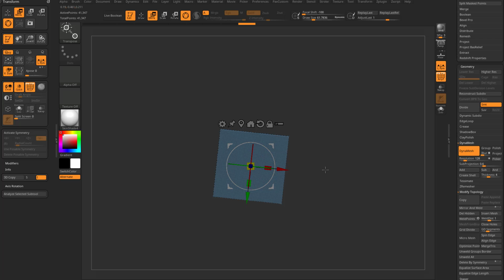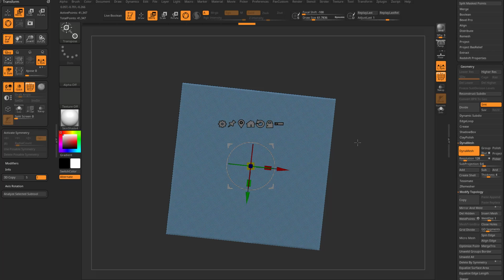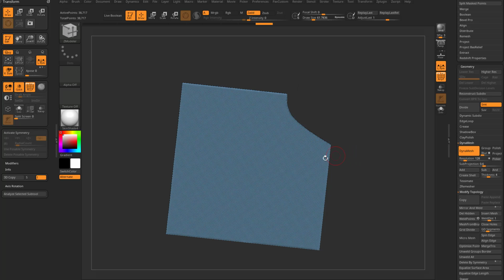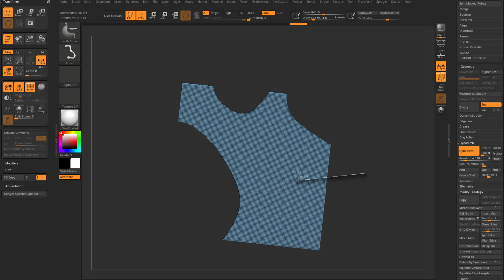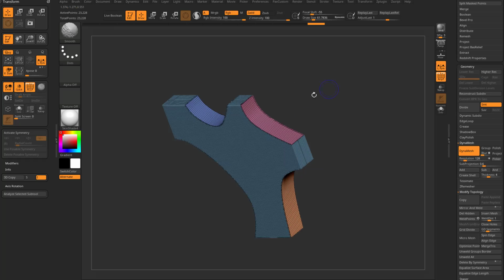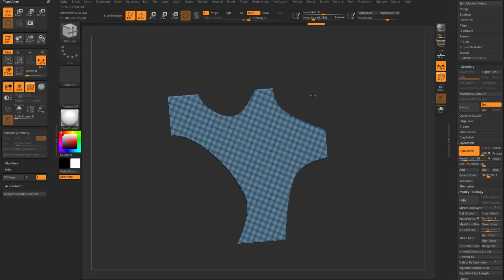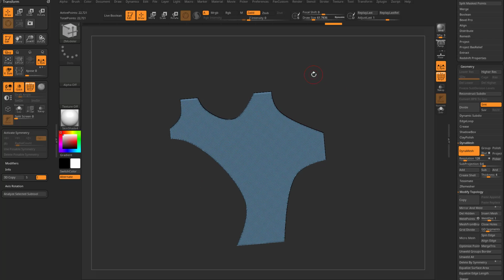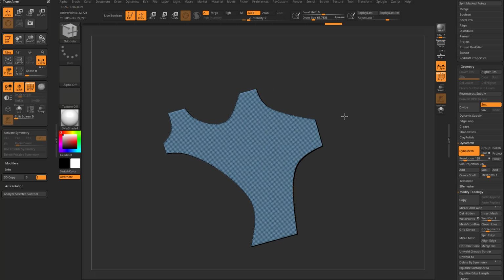And then click that Z or whatever axis you want to cut in. In this case, the Z is what I want. And that'll point that camera straight in the direction of that gizmo. So now when I'm using this knife curve, I can be confident that I'm looking straight down at these faces. So it's cutting straight back. If I tried to eyeball this into place, I'd probably be a little bit off. It's going to cut at a slight angle back.